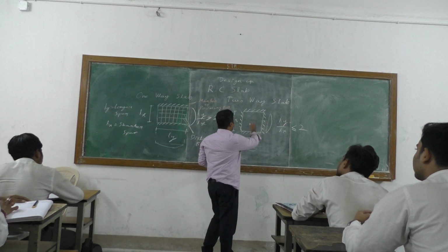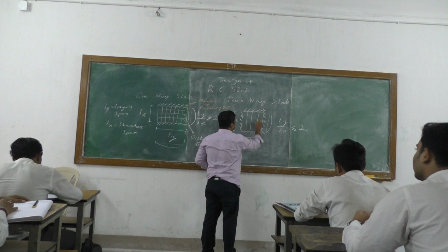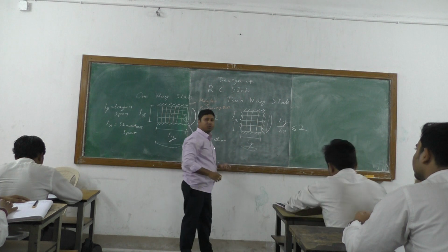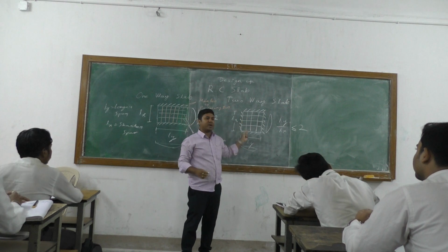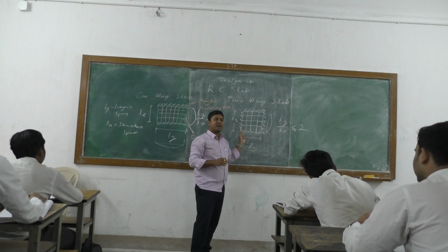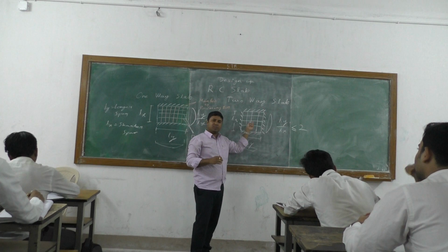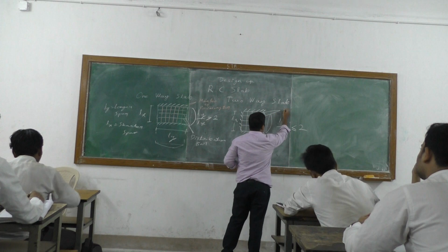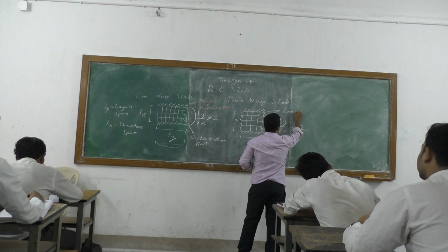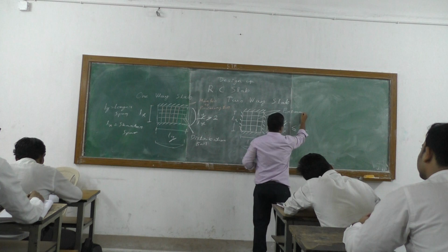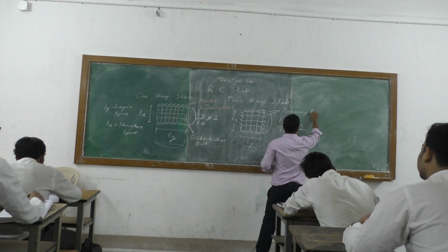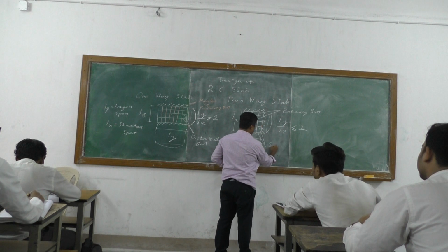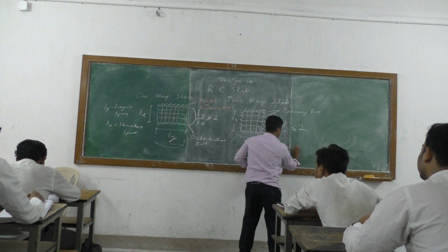In the case of the two-way slab, since both directions carry almost equal amounts of bending moment, the reinforcement in the x and y directions is similar. The importance is similar. So one direction is your primary, and the other direction, the y direction, is secondary.